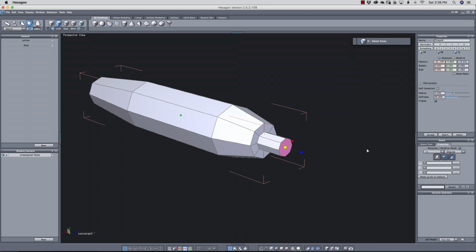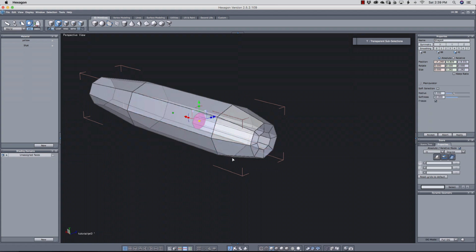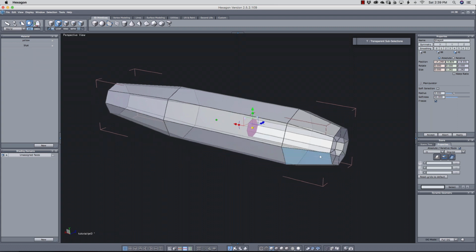There, we just made our first fast extrusion. Now let go of the command key, and with the face still selected, I can drag this extruded face inward, dragging the red arrow, and that makes our hole. And I can press T for transparency so we can see through it. Here I don't want to go all the way through, just about midway.